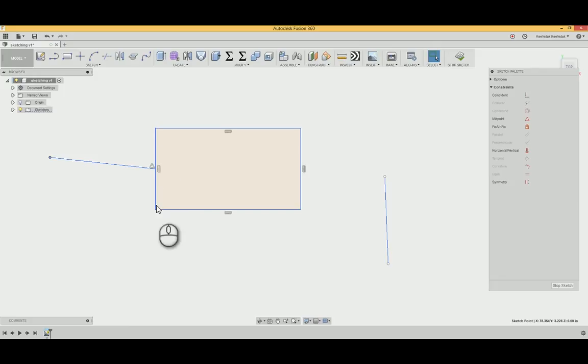Okay. You can also have things be midpoint to each other. So click on midpoint again. You're going to click the line, the other line. Oops, okay, there we go. That's why I always say clear your cursor with escape, because sometimes you have something selected and you don't realize it, and you apply a constraint inadvertently.